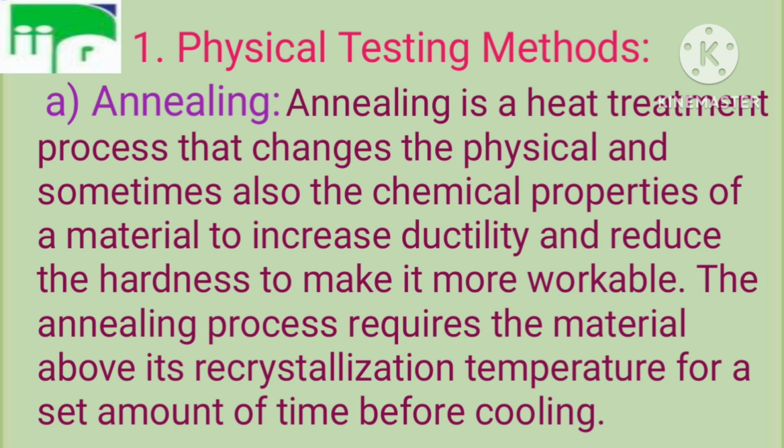Annealing is a heat treatment process that changes the physical and sometimes also the chemical properties of a material to increase ductility and reduce the hardness to make it more workable. The annealing process requires heating the material above its recrystallization temperature for a set amount of time before cooling.